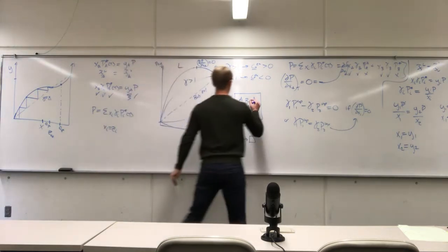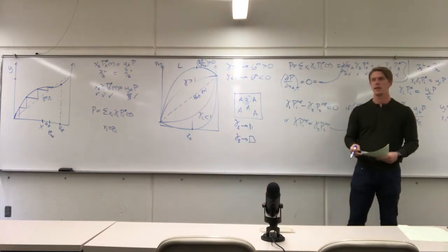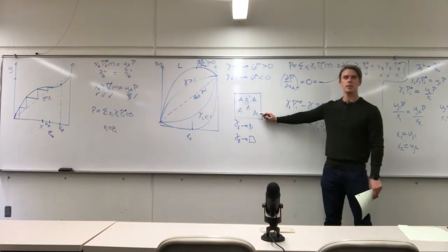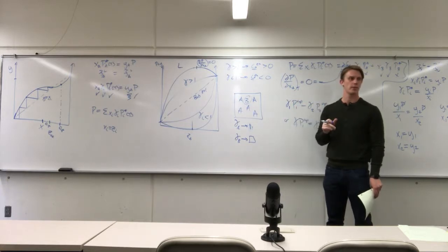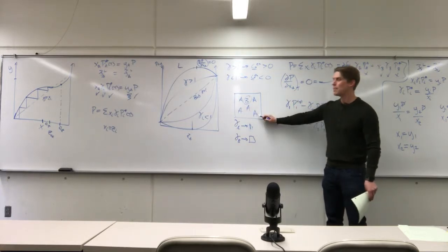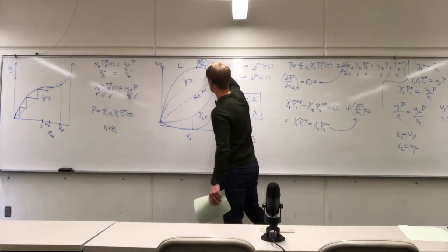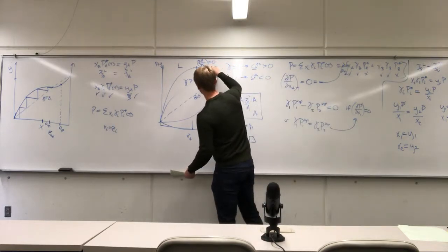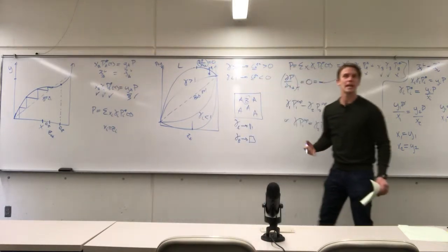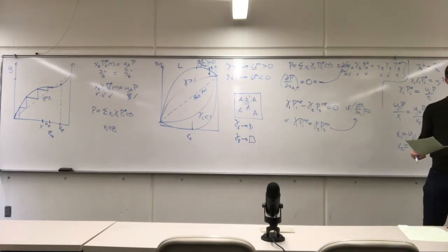So what happens then is normally, maybe B is a really non-volatile heavy species, but he's so unhappy to be in a party of all A molecules that it just wants to get out of there as soon as possible. So even though A may be the more volatile species, in fact, it's going to be B that is preferentially leaving the liquid phase. B is going to be really wanting to get out of that liquid phase. And this contributes to the non-ideality of the system.